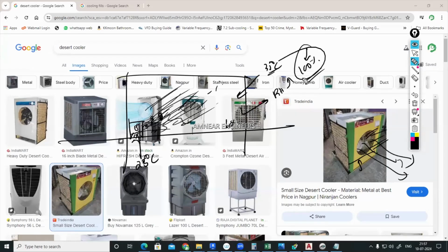So once the relative humidity within the space becomes 100%, the next process that is going to happen is it will be simply spraying the water somewhere near, and also it will be wasting some electricity. Correct. So it is not an effective cooling technology. Rather, it may create some discomfort for the people, because if the relative humidity within the space is very high, it may create some sinusitis issues.